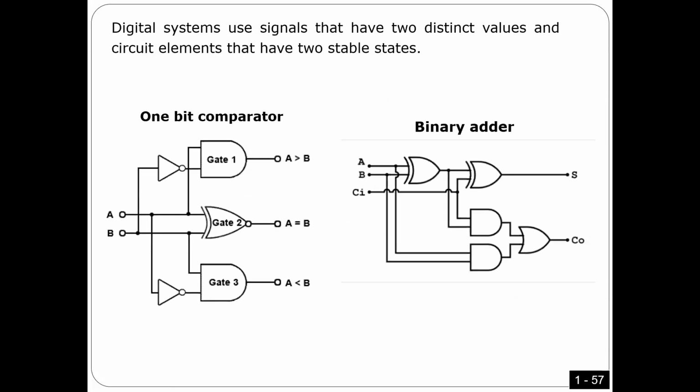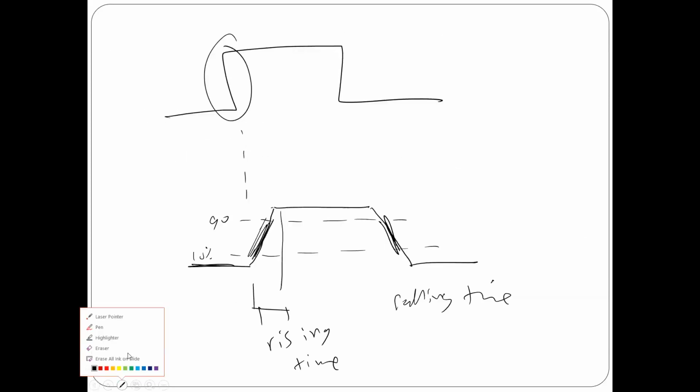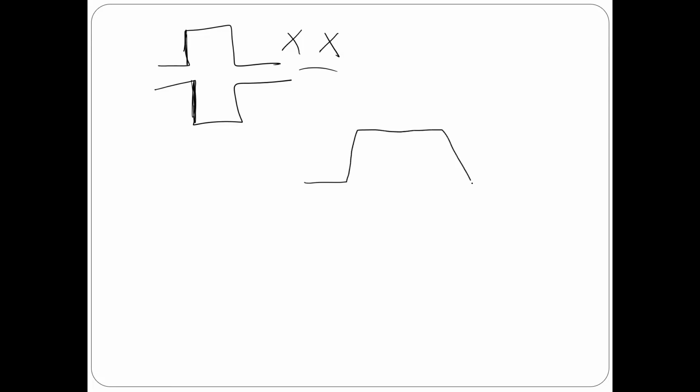One more thing is about propagation delay, because that's what you are going to see. I told you if I input this way, the output has to be this way. For sure, it can't be, because that means the transistor or the circuit takes 0 seconds to react. Once the input is 5, it would react in 0 seconds to 0. This is not the reality. The reality is there is a delay. So in reality, in the coming lab, for sure there is some increase here, decrease here.